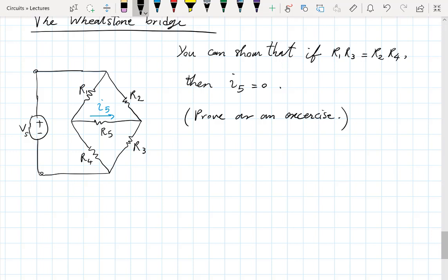This is not really anything new, but I just wanted to bring it to your attention. So you have a bunch of voltage sources, you have a bunch of current sources, independent ones. If you replace all the voltage sources with short circuits and all the current sources with open circuits, which means you have set all the independent sources to 0, then whatever equivalent resistance you see between the 2 points of interest, that's your Thevenin resistance. Okay. It really follows from all the discussions we've had before. Just wanted to point it out.